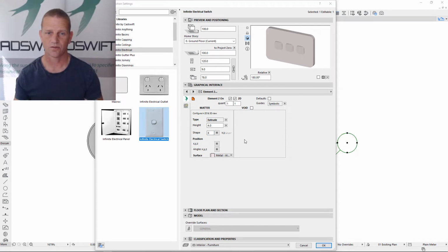Now before we change this to a revolve, this is an 8-sided shape that won't necessarily go into a revolve very easily. It'll probably have some negative values in it as well. So it's best to temporarily turn on this default, so it sets it back to a more default sort of shape that a revolve can handle. So we just click default and then we turn that off again. It brings us back, so you can see it's defaulted now to this large element here.